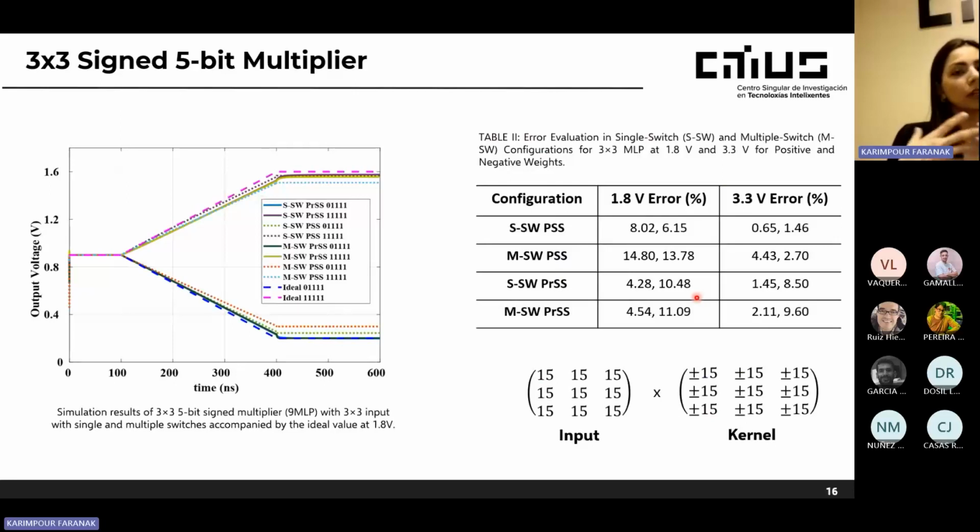If we want to increase it more, the error voltage decreases, but the slope, the deviation between the difference in voltage, becomes so big if I increase the size of the transistor. Because of that, I just increase it until 1 micron to have the better value in error.